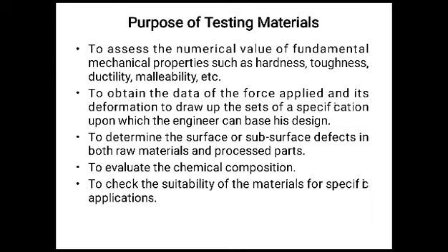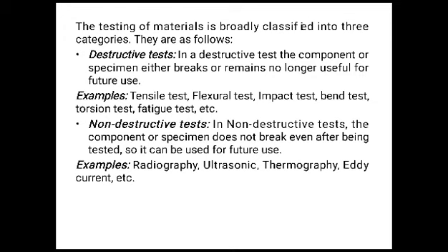What is the purpose of testing? To assess the numerical value of fundamental mechanical properties such as hardness, toughness, ductility, malleability, etc. To obtain the data of the force applied and its deformation, to draw up the set of specifications upon which the engineer can base his design. To determine the surface or subsurface defects in both raw materials and processed parts, to evaluate the chemical composition, and to check the suitability of material for a specific application.